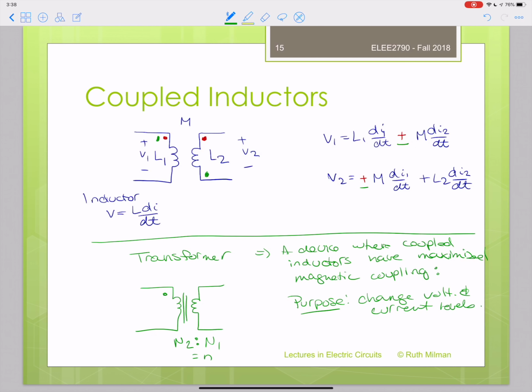So you may think about times when you travel and you're going to a country where the outlets have different voltages than the ones that our stuff is used to, and you have to make sure that the power doesn't blow the circuitry inside, and you might bring a transformer with you. The whole purpose of that transformer will be to change a 120 volt plug to a 220 volt plug, or a 220 volt plug back down to a 120 volt plug. Note that when those transformers do that, they don't change the frequency, they only change the actual voltage.